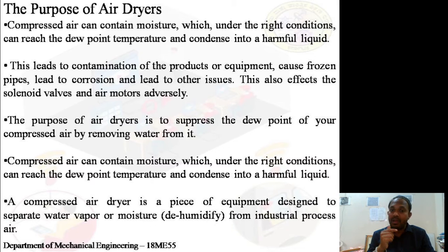So these problems all occur because of the moisture content present in the air. One interesting thing is that these water particles may evaporate in extreme temperature conditions, or they may freeze in extreme cold conditions. Once frozen, it becomes ice, and ice is a tough material that obstructs the movement of the particles. Is that clear? That will cause major trouble for pneumatic systems.